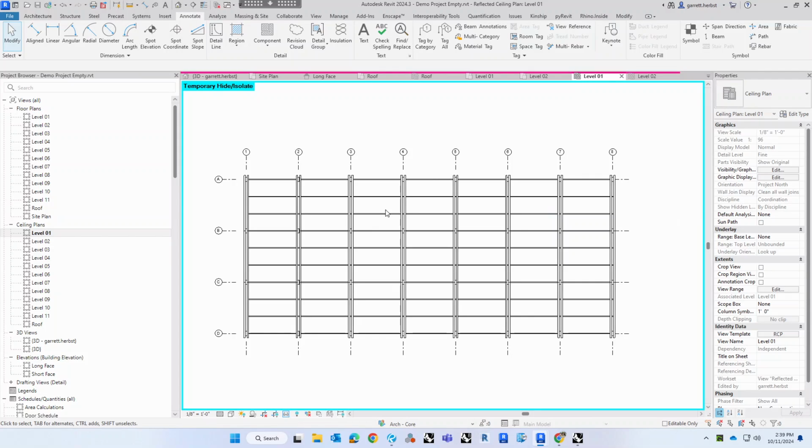And then if you want to be super specific, since realistically the purlins are not supposed to run into or through the beams, but are supposed to sit on the face, you can offset all these. There are two different things. One is your little blue dot right there. That's connected to your structural grid. That's the thing that's linking it to the grid. So don't move that. But you can change this little offset slider that essentially pulls the model geometry back from the grid. And when I do that, it'll populate the dimension automatically right there.